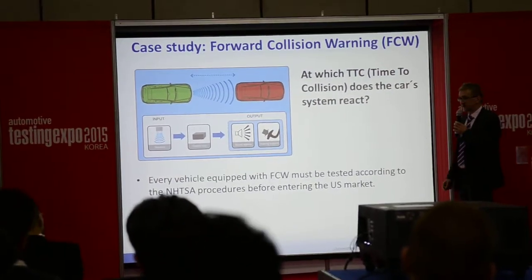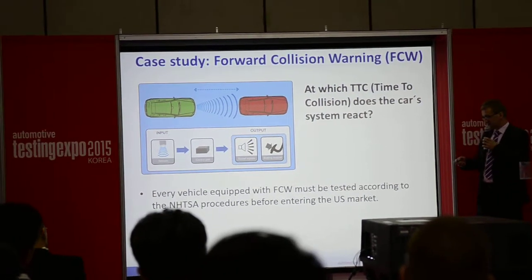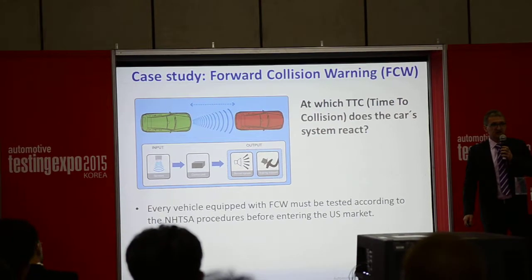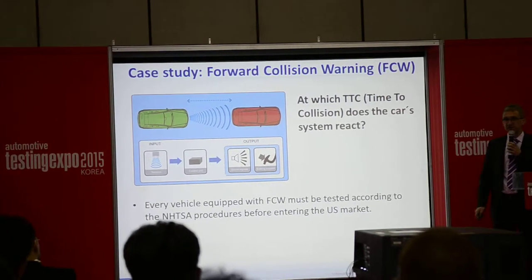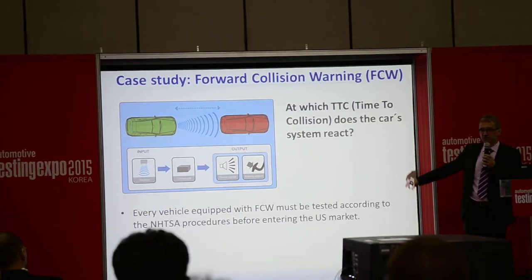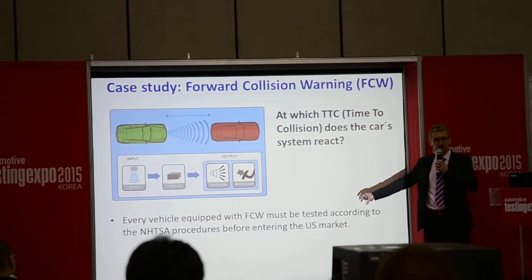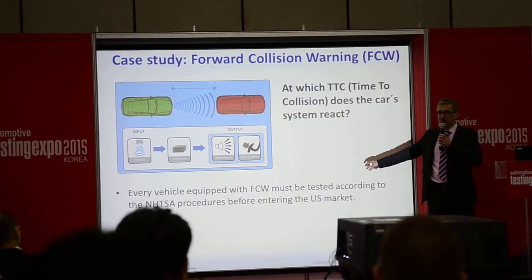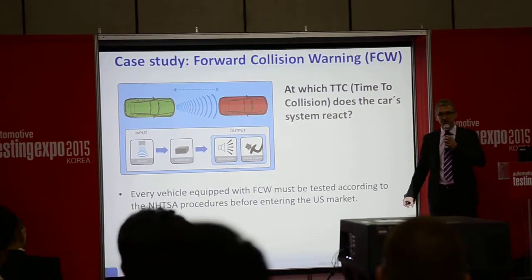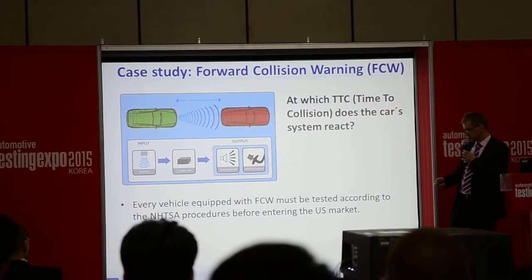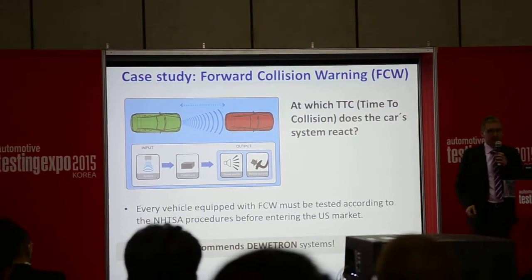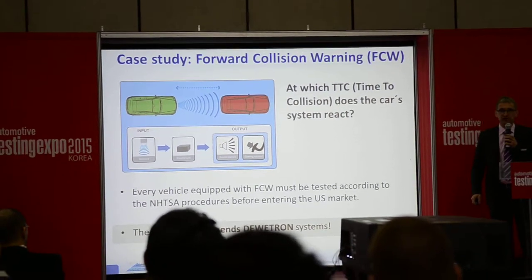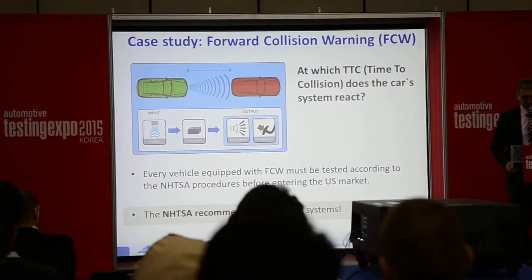One more word regarding this testing is in the USA, the NHTSA developed testing procedures for the FCW. And of course for the USA now any car anyway needs to be tested according to these procedures, but most others also use the NHTSA procedures for testing FCW systems. And maybe also mentioning the NHTSA is recommending to use the DEWETRON system for such kind of testing.